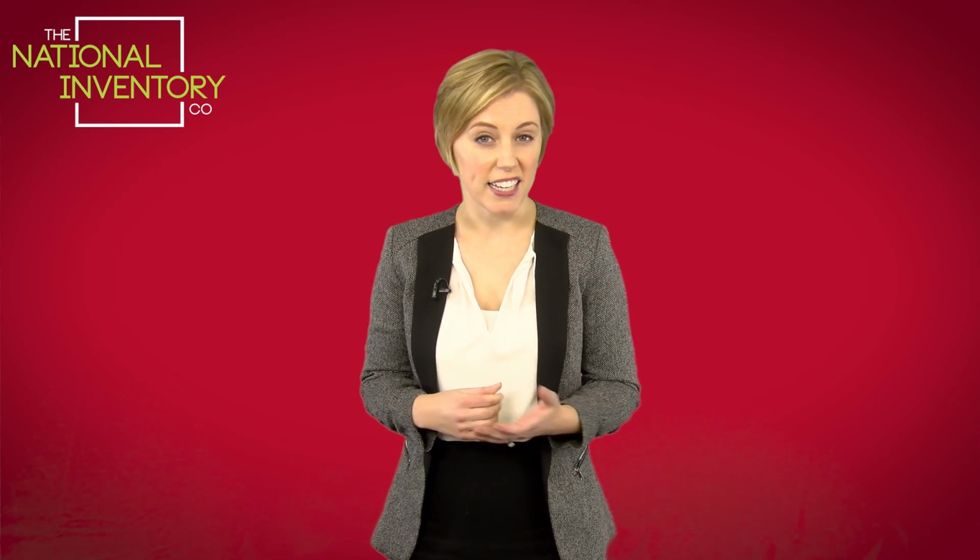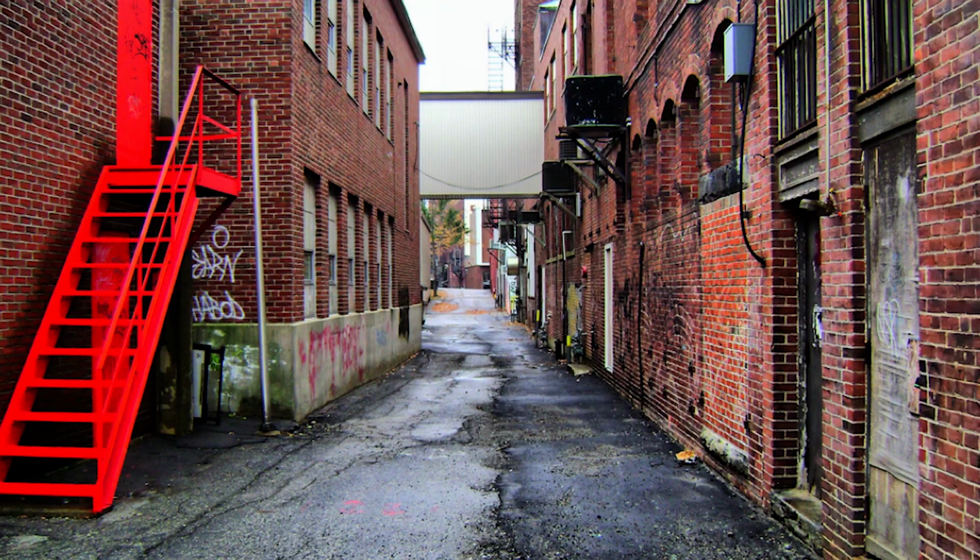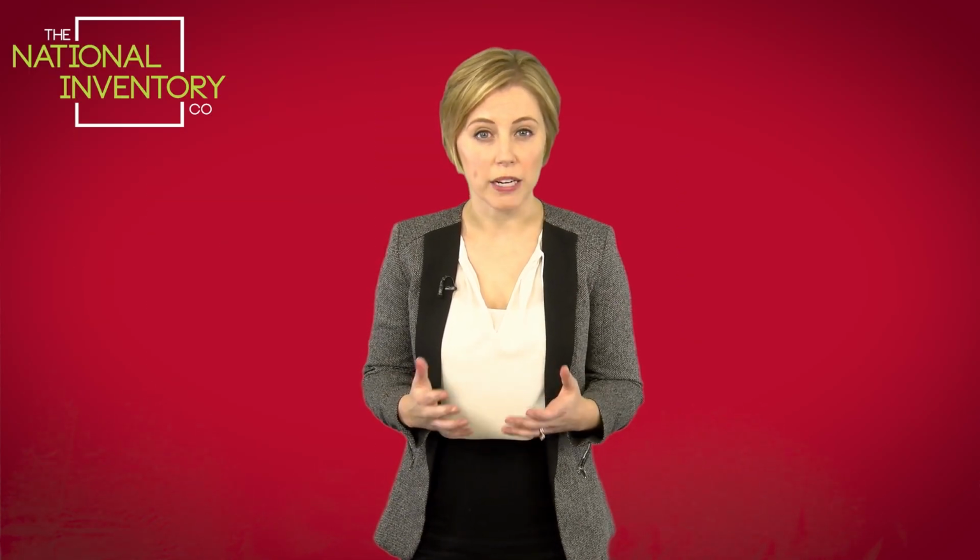place of safety. In other words, the entire escape route up to and including the final exit from the building or property must remain unobstructed at all times, while the distance people have to go to the escape route must be as short as possible. In the picture, it shows a red fire escape, but there's no suitable lighting outside of the property and the alley is narrow. So the tenants have to walk down the alley to be able to get to a place of safety, which will involve them walking past the burning building. This is not a suitable exit strategy.